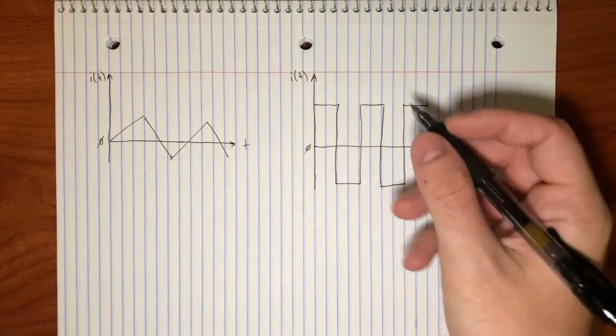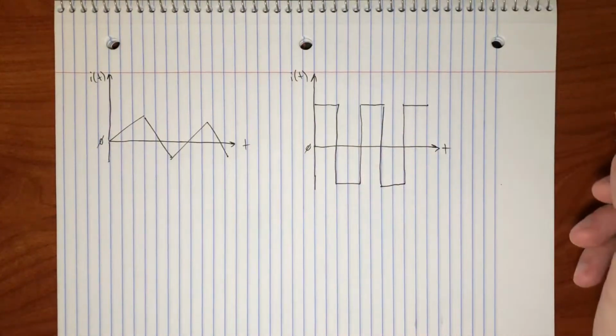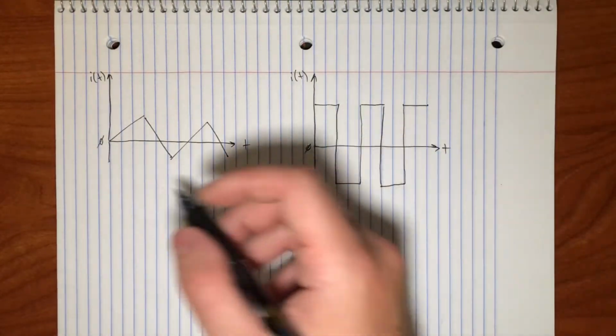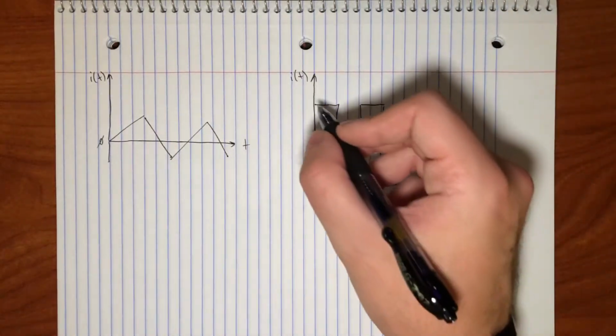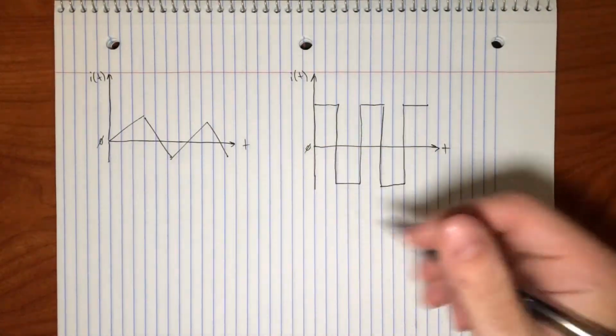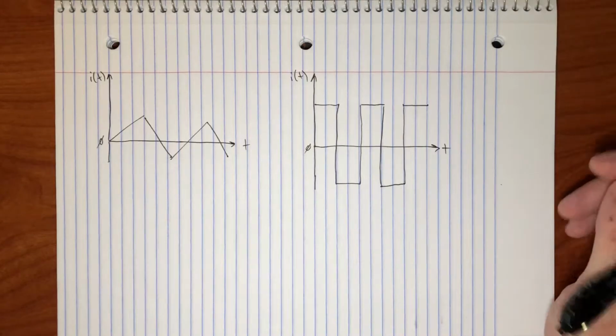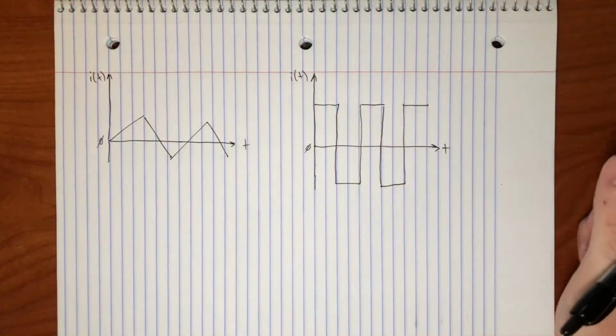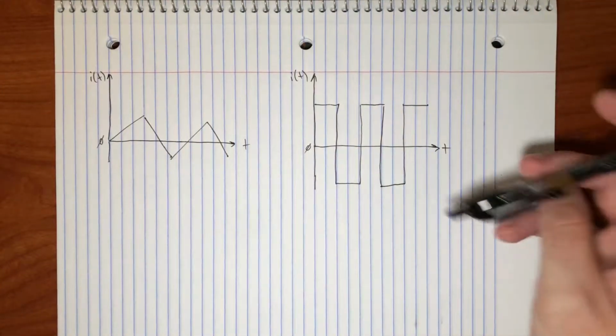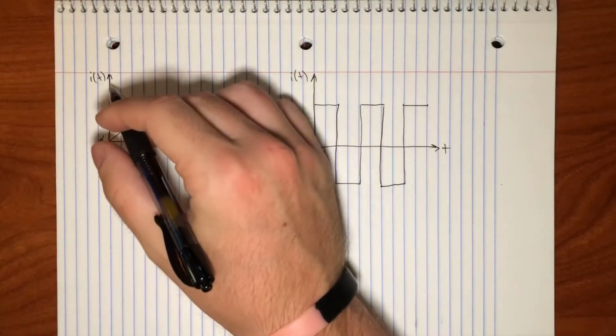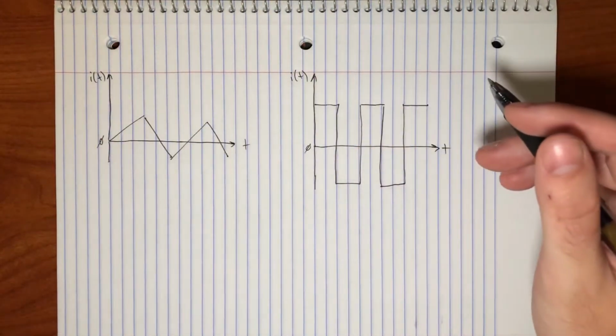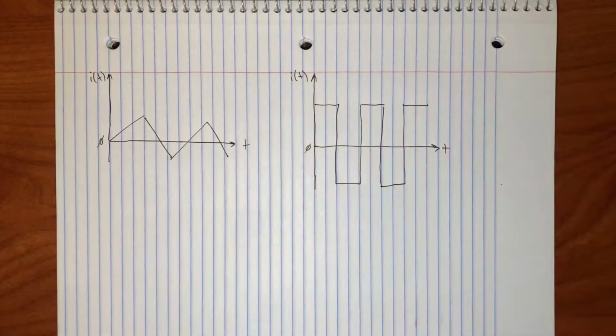So these waveforms, assuming they continue for any meaningful amount of time, you would say are periodic. This sawtooth is periodic. This square wave is periodic, and the sinusoid I drew on the last page is periodic. That's usually what we're talking about when we say AC. It's something with zero crossings, describing that the current actually changes direction, and it's something that's time periodic.